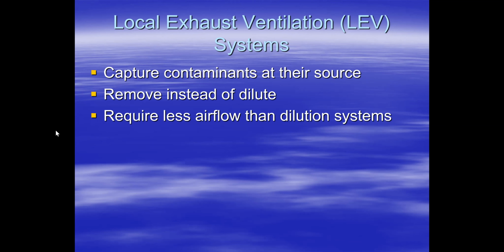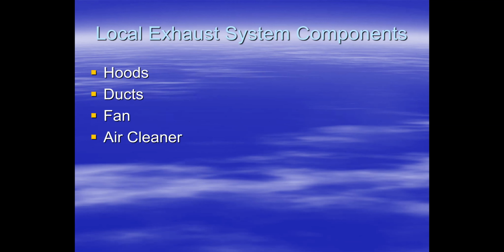And I've actually seen systems, particularly with wood dust systems, where they did not do a very good job of maintaining their blowers and their air cleaners, which put a lot of resistance in the system, which slowed the air down sufficiently for the dust to settle in the ducts, which later on ignited. Another example of that would be the Imperial Sugar in Georgia that blew up, I think it was 2011, maybe. My data on that is a little off, in which they had a series of explosions, because when they had one explosion, it suspended more dust in the air, which then ignited, which caused another series of explosions. So maintaining your system is really important.